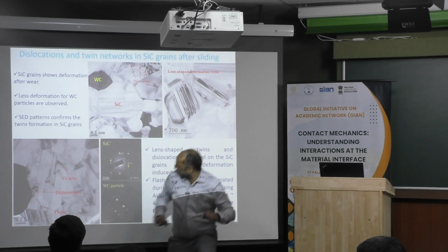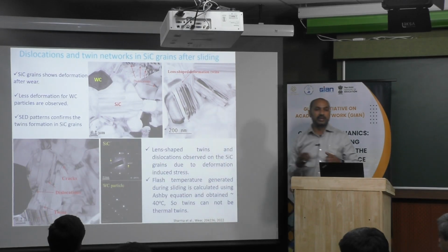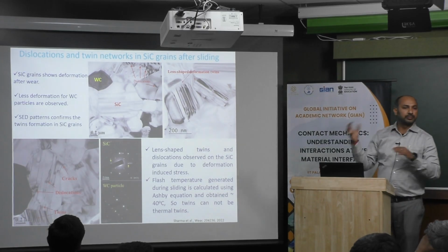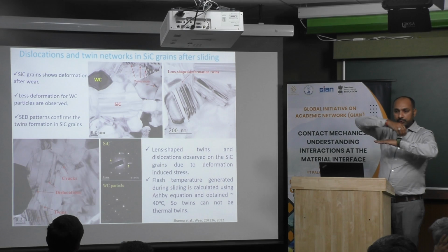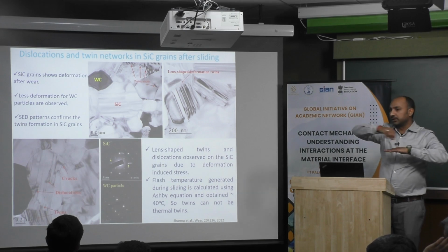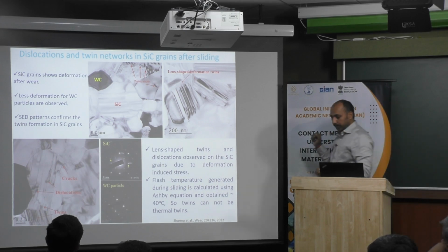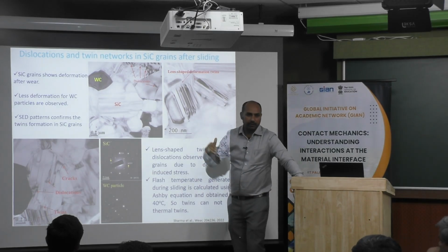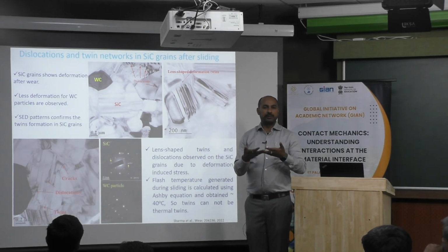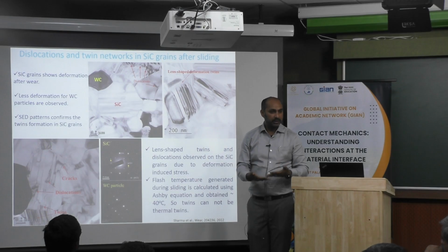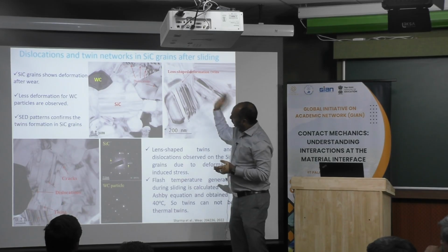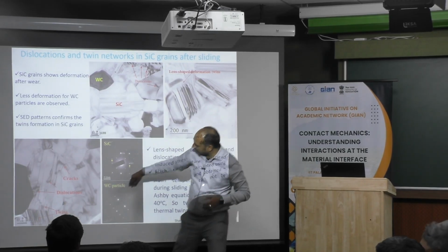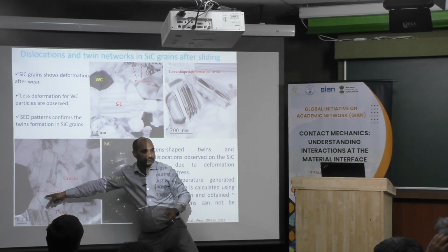These small cracks, we can see, are getting generated out of the dislocations forming during this reciprocating or continuous sliding condition. And for confirmation of this, we can understand, maybe we are sintering this surface, we are having tungsten carbide and SiC, so it could be thermal induced stresses. So yes, we can consider these stresses as thermal induced stresses.